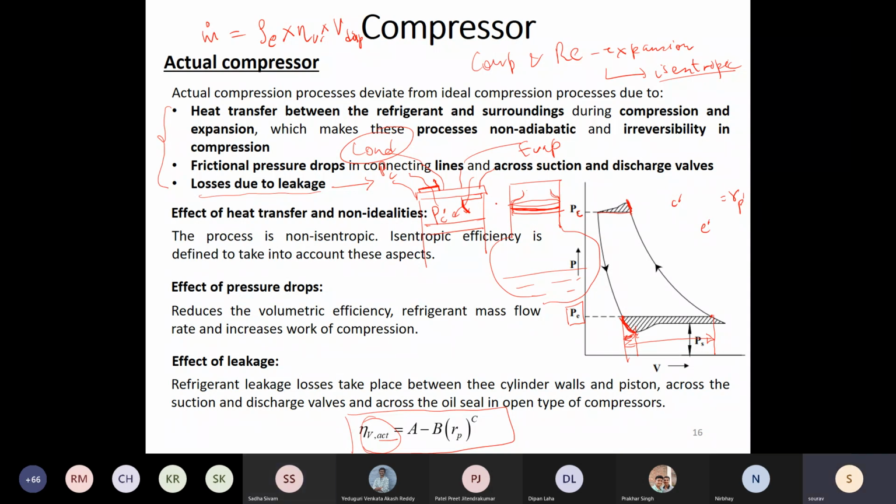So that amount of additional overpressure the compressor has to provide, which means that you expected in the previous discussion that the valve should open exactly at this moment. The valve will not open exactly at this moment. It will open somewhere here. Let's say you apply more spring force, or if you provide a much more rigid plate, it will require more overpressure.